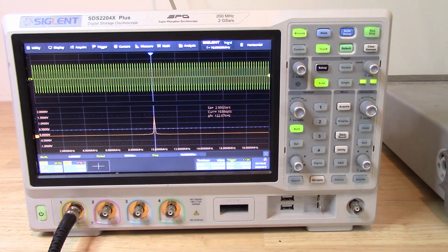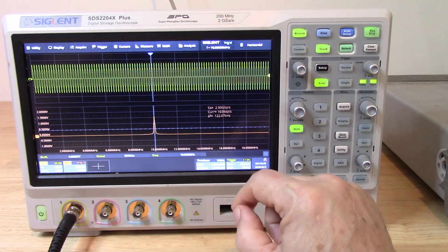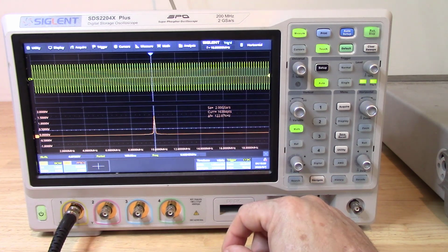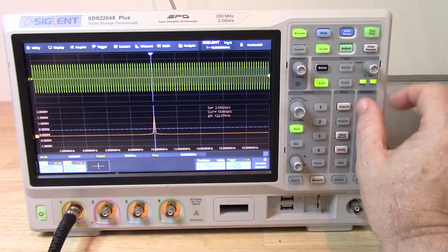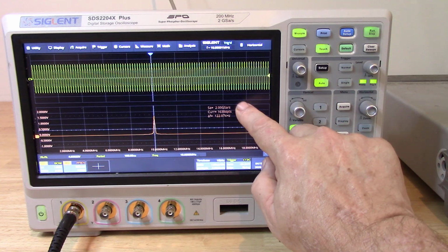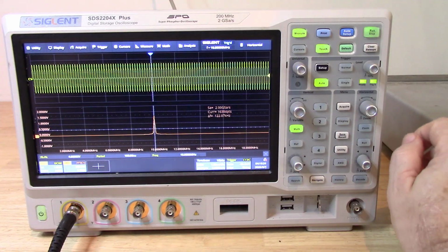And one of the things you're asked to do, it's a different frequency than this, but you need to do a screenshot of both the real-time and the frequency domain spike for the lab, and I think it's 1 megahertz instead of 10 megahertz. To demonstrate alias, what we're going to do is change its sampling frequency. You can see right here it's 2 gigasamples per second.